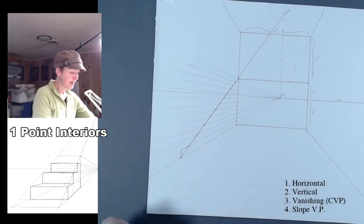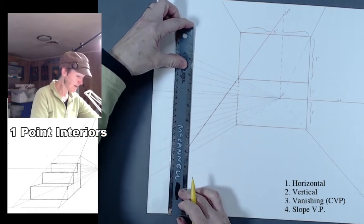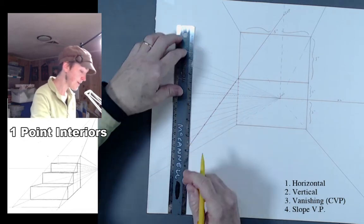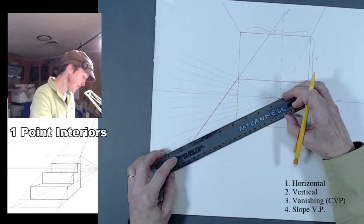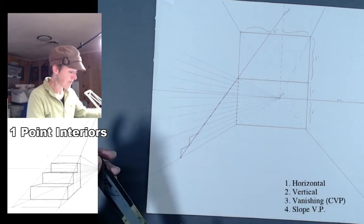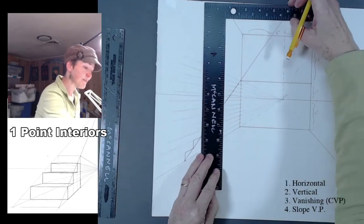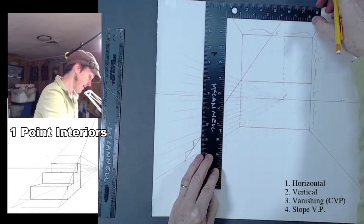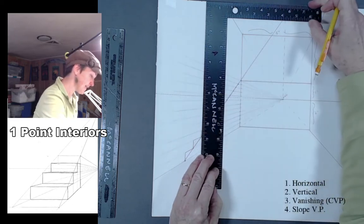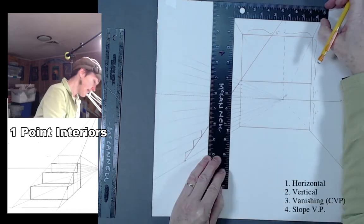So from this next point, again, just a true vertical line. Use your grid paper underneath your drawing paper if you need to, or use a T-square or your triangle to make sure that you keep those verticals really nice and straight. Otherwise, we're going to have some problems with distortion. So I'll maybe try this. Keeping that square along the top edge, and each line just goes up as far as the next line above it. It's not going to have to extend all the way up, just enough to reach that next step.